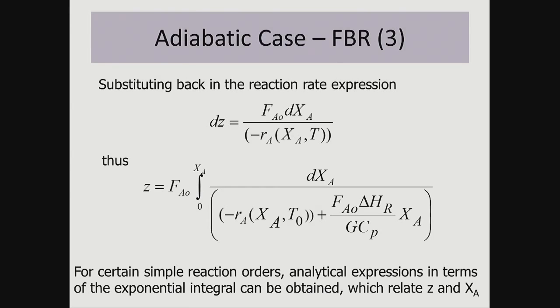The question is, does that kill your catalyst? Does it blow it up, the catalyst and the reactor? Or is it manageable within your design constraints? If it's endothermic, it's not as serious, because you don't generally kill anybody, but it is fairly serious, because if it goes too cold, it turns itself off. So the reaction stops, so you'll get no conversion.